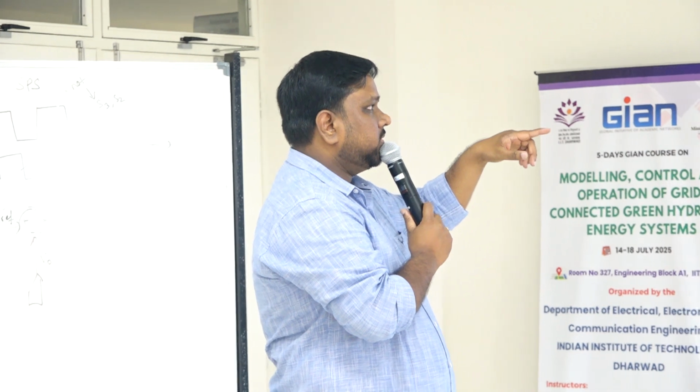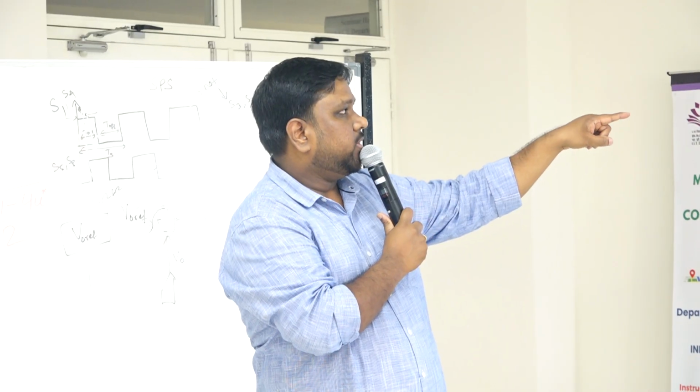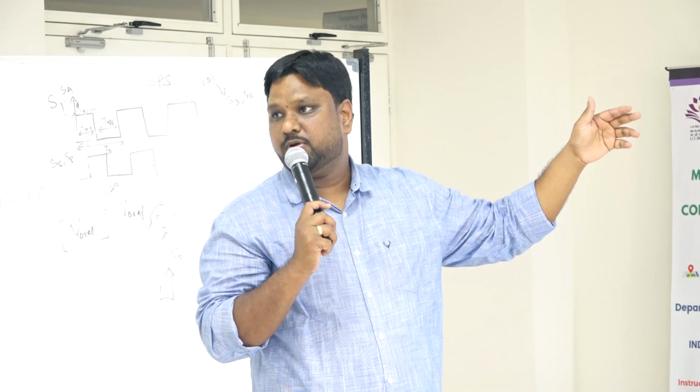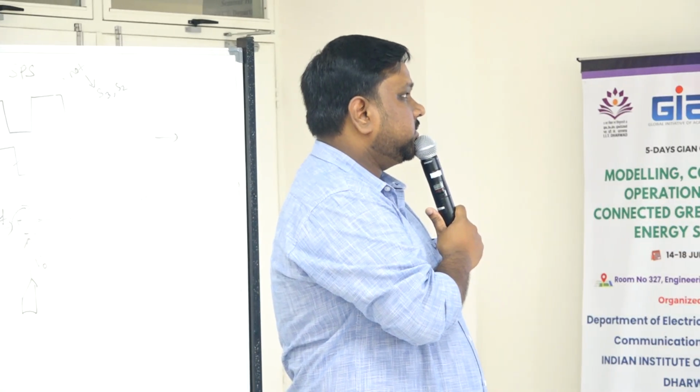Can you open that stair generator? If you see, at 0 time my voltage is 262. At 0.05 time, I step down from 262 to 209.6. At 0.1, again I step up to 262. So during those transitions in the reference, we are going to see how V0 is tracking. Understood? Okay, now we'll run that.